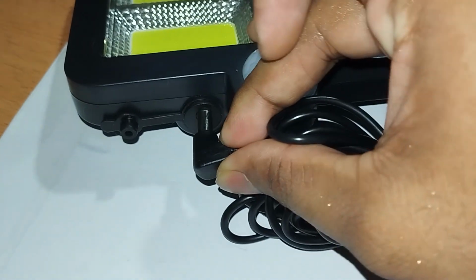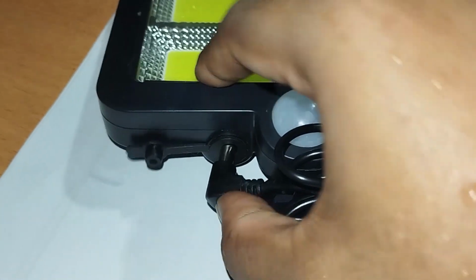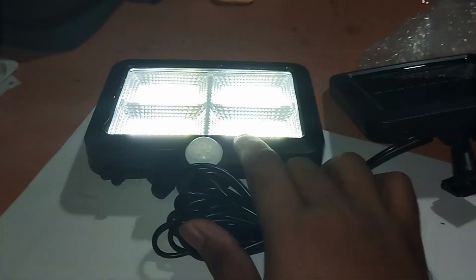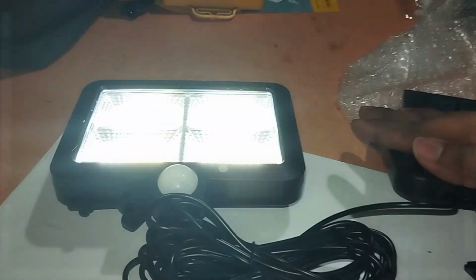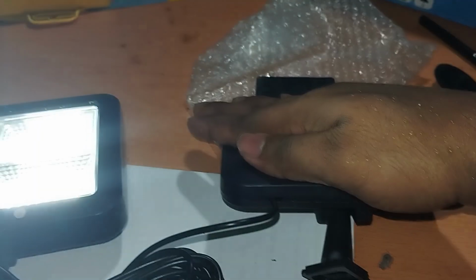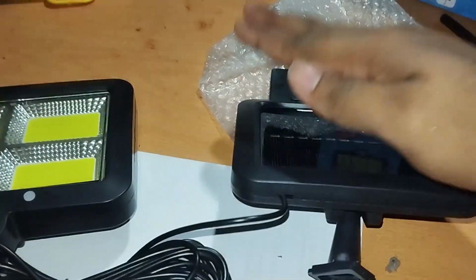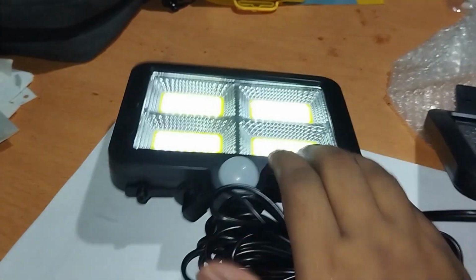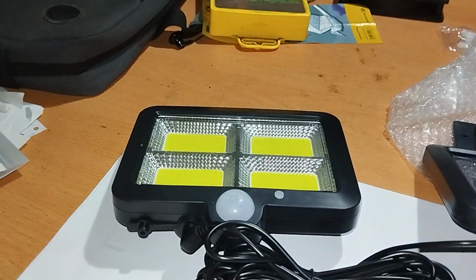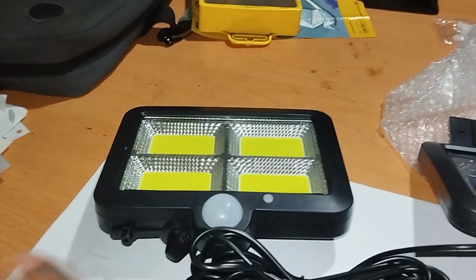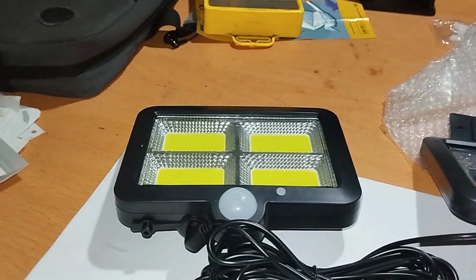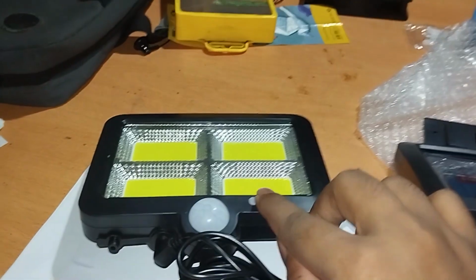Every day it is turned on, turned off, and charged, and if the battery capacity is increased, you need a larger solar panel to charge it at an optimal C rating, because I do not want to degrade this C rating. That leads to some complicated things, because increasing the battery capacity needs better charging. Otherwise the battery capacity is useless, with a tiny bit of charging and a useless amount of capacity. That's the additional cost. If you jump to the next stage, it can be advanced premium. Increasing the battery is advanced premium.